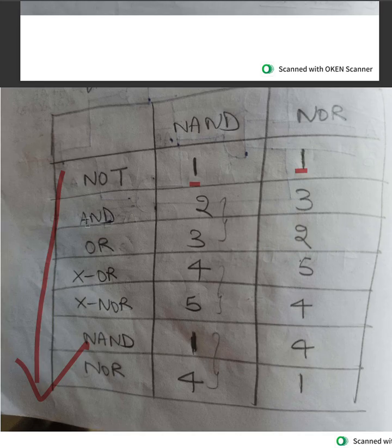Okay. So if you have to make an AND from NAND, it's simply two NANDs. NAND means A into B whole bar. Again, if you apply a NAND, A into B whole bar, again whole bar, which is two bars, which get cancelled out, and you get AB, which is simply A and B. Okay, so that is how you get this. So again, for OR you did the same thing. You took A and B separately, A bar into B bar, again another NAND gate. Okay, that way you got three NAND gates.